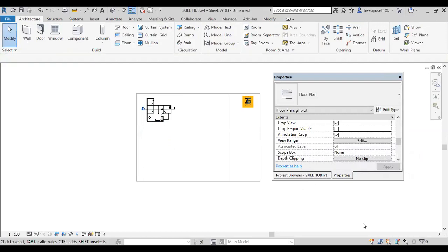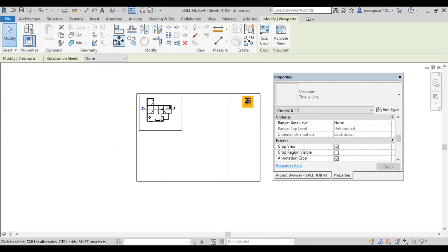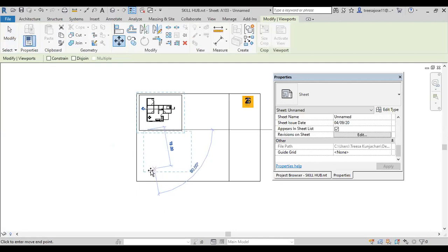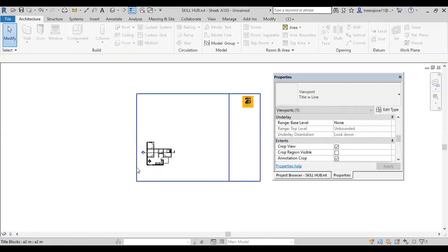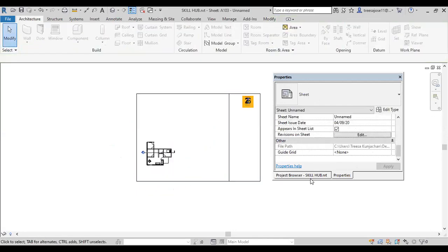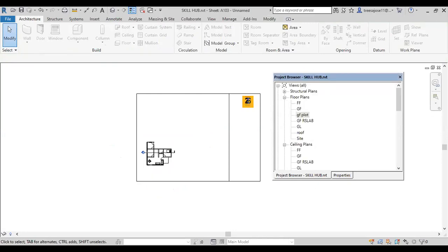Then after that you can import the section, because normally in our drawing the plan will be in the bottom section. You just place the plan. Just select this. Add the elevation. Select the elevation. For the elevation also, it is better that you make a copy of this one, then drag it.